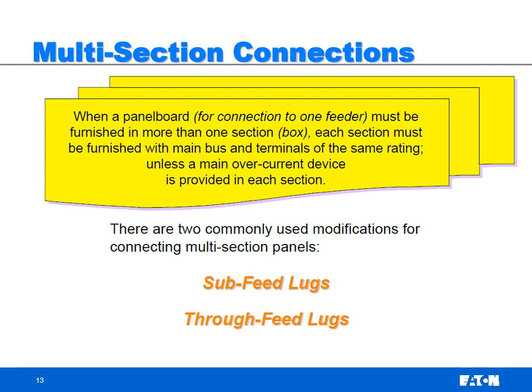So there are some physical limitations on why it just makes sense. So one of the things that can be done if you've got more than 42 circuits, and it's very common to have 84 circuits, is you've got basically two of these panel boards, but you only need one main breaker or one cable feed to this.